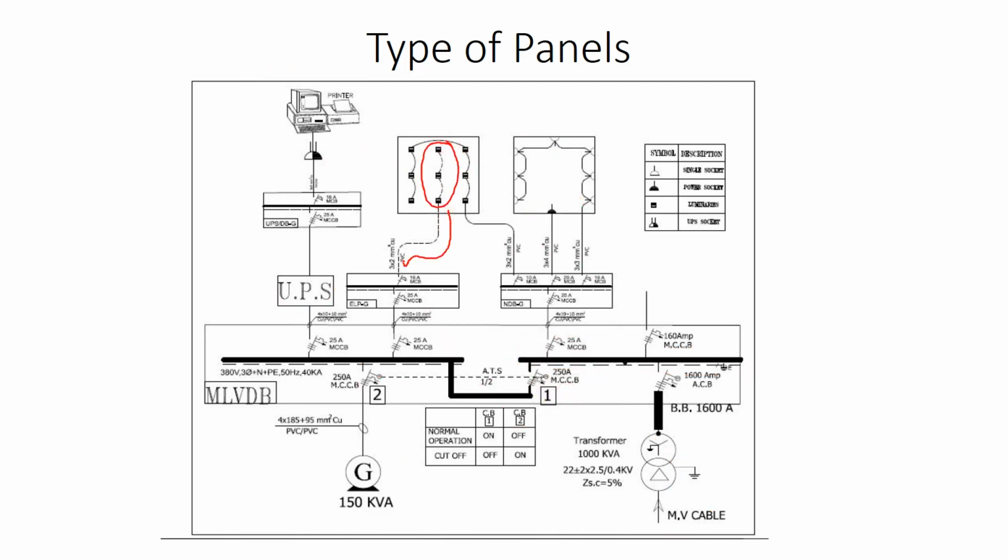Since they are connected to the emergency panel, people can see and walk in the corridor, for example, or in rooms. So they keep 3 luminaires connected to the emergency generator. Now you have to understand that this generator, for example, will take 30 seconds in order to operate. During this time, these luminaires are shut down or off.